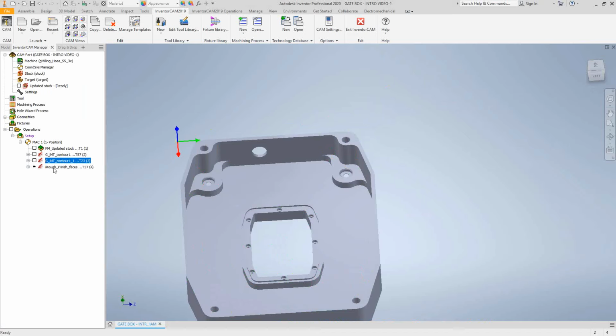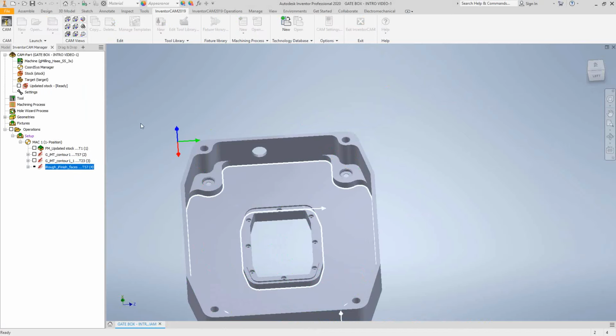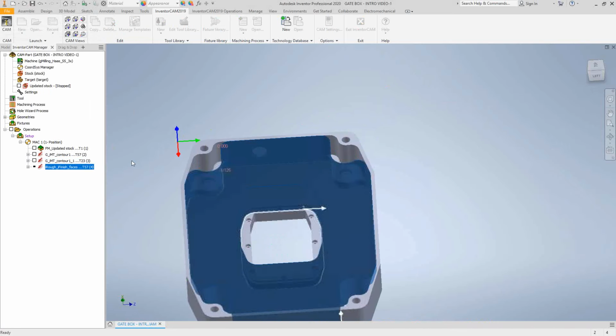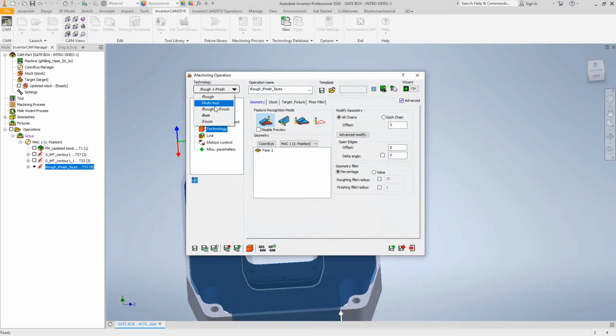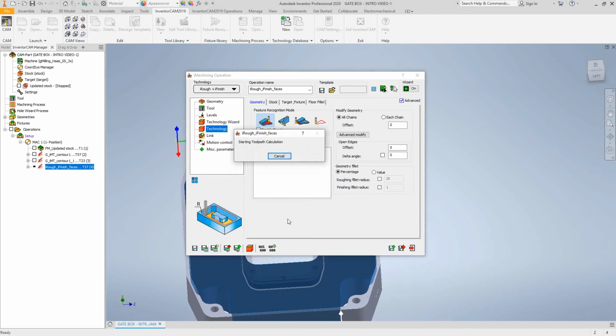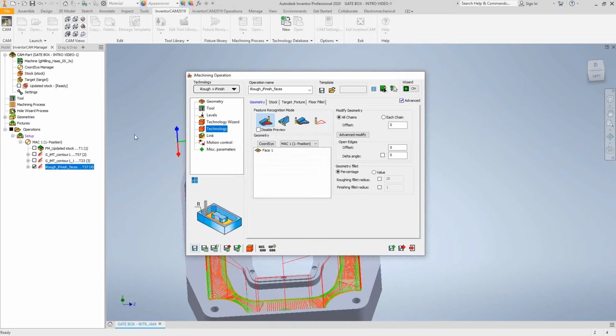If I needed to, I could actually set it up as a separate iRest simply by doing the same sort of thing. I can open up the toolpath, do a save and copy, and then switch it to iRest. Now, I wanted to show you some of the last couple of ones here. Let me just do a save and calculate on this guy so we can have this up to date. And then the 3rd and 4th modes of geometry.